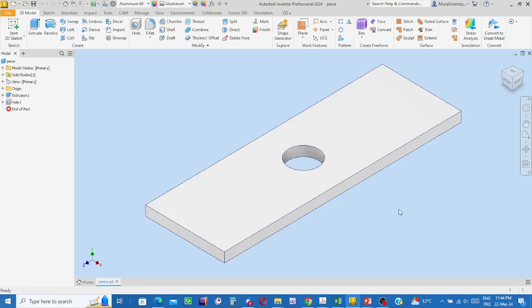Okay, so obey the recommendation. In the vicinity of the discontinuity, use a smaller sized element, finer mesh, greater number of elements. But for the other part, sufficiently away from the discontinuity, use a greater mesh size.